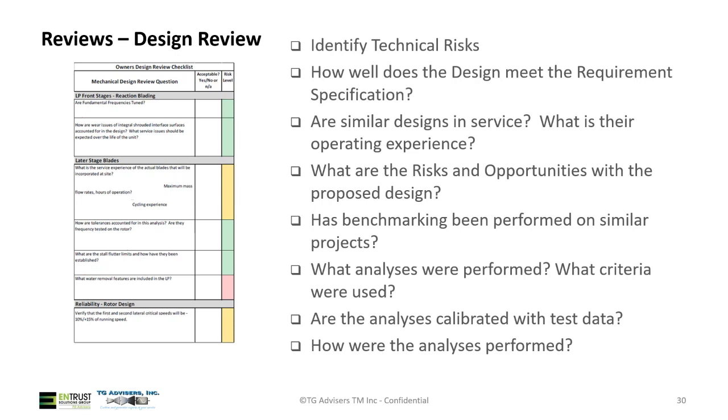So off to the left, you can see in our checklist, this is showing some LP blading questions, like are fundamental frequencies tuned? How are wear issues of integral shroud interfaces accounted for in the design? So on and so forth, service experience, etc. This is usually a fairly detailed, involved process, and we recommend that everyone go through this process when you're going through a retrofit, just to understand and make sure that everybody is clear on what you're getting out of it.